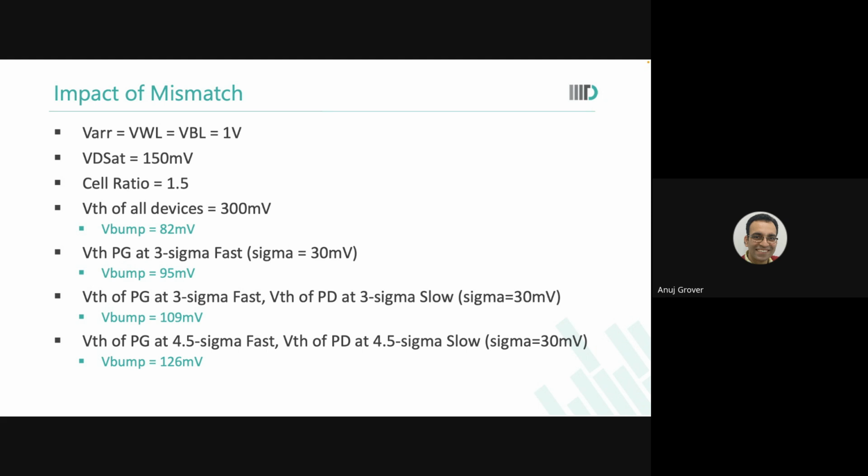You do a small mistake and the entire chip goes into the trash bin. Okay? Significant yield losses can happen if you do not take care of 6 sigma on each side when you're designing memories. So do not get confused with 6 sigma for software here. 6 sigma for software is 3 on this side, total 6. But 6 sigma in memory design is 6 sigma on each side. Okay?